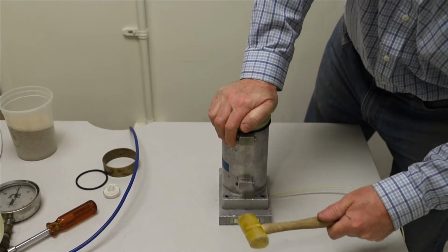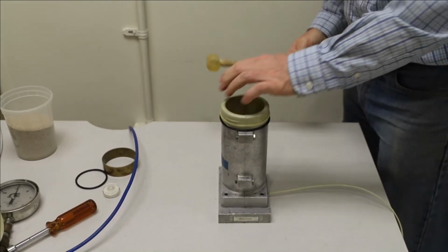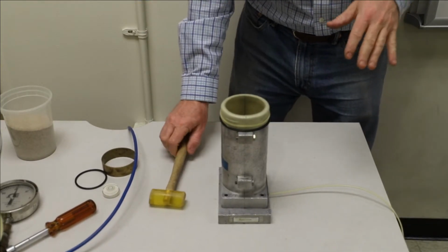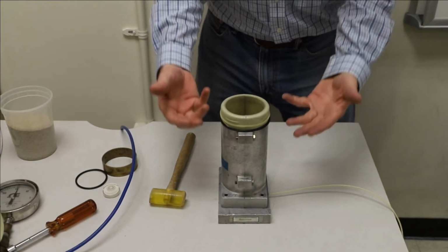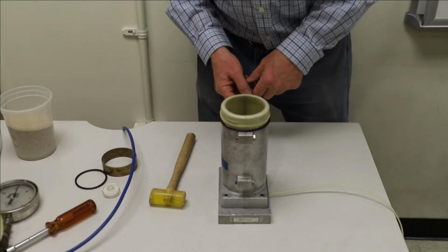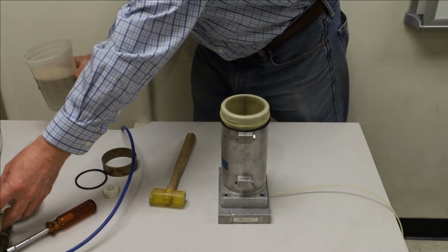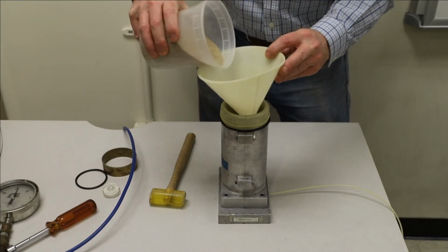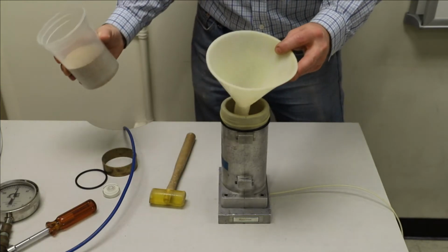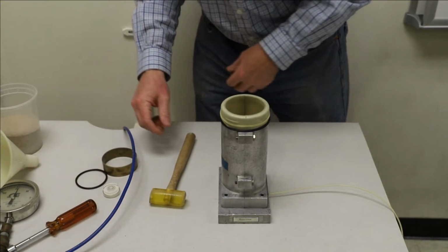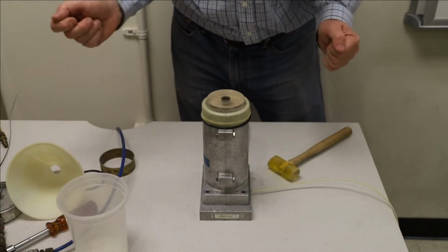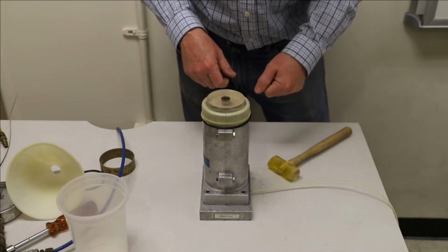We want to apply it uniformly all around the specimen, with the idea that these vibrations allow the sand grains to rearrange. Gravity is pulling them down all the time, right? But if we shake them around a little bit, they're going to fall into denser configurations. And so we're going to do that 5 times to fill up the mold, getting about 20% of the sand each time. All the soil is in and tamped, vibrated heavily.